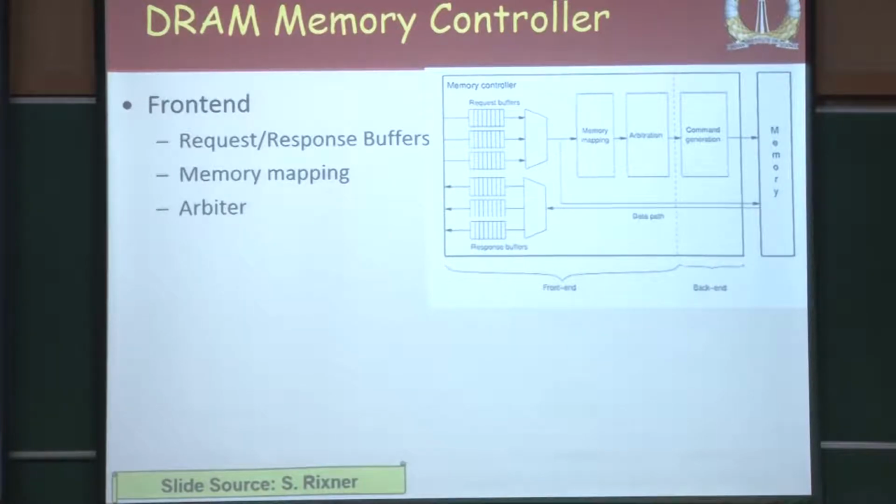To memory you can simply think of it as a read, but then the memory controller is going to split this into one or more commands depending on what state the memory is in. If that particular row is already there in the row buffer, it can only give a read access. If that row is not there, it has to give a precharge, activate and read. So, the memory controller has to take the appropriate action. Every read command is going to be divided into one or more commands for the controller.